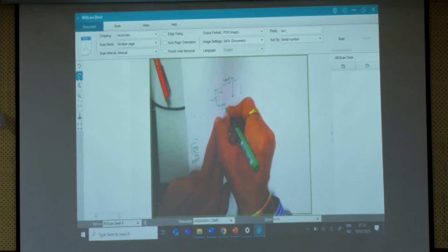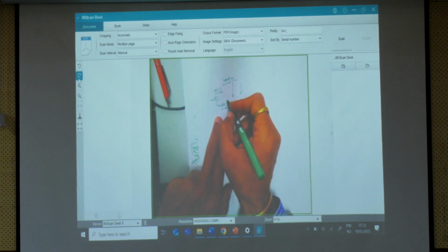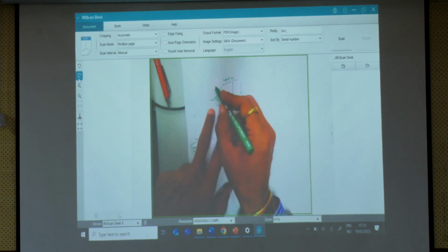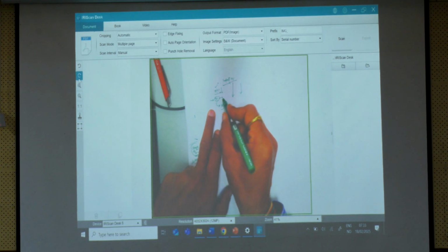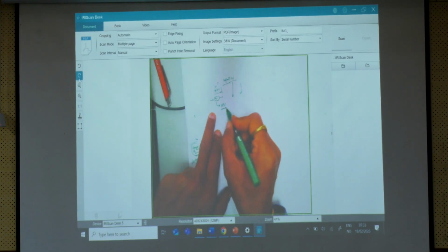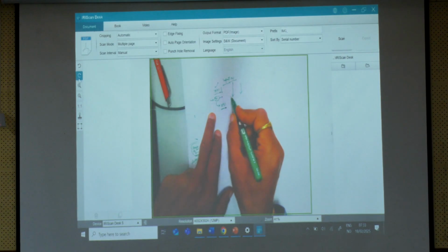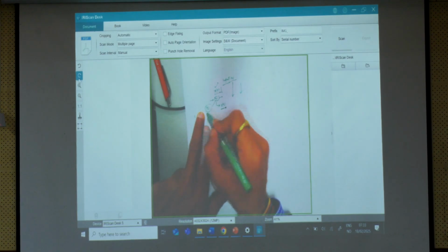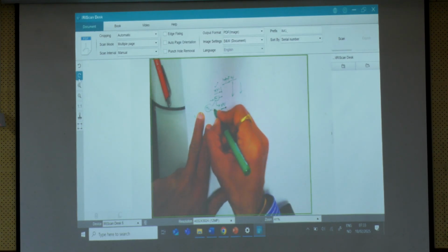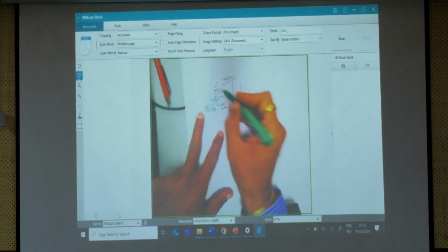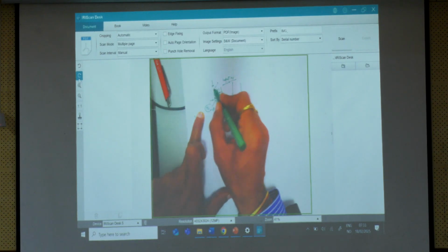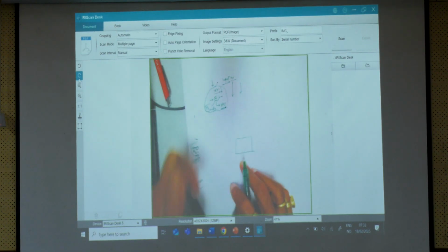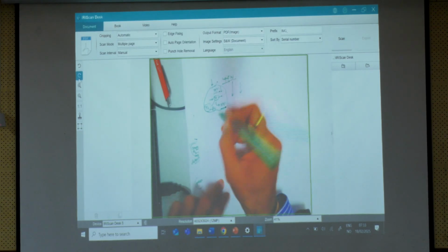There are a lot of models, they are available even in the MATLAB Simulink also. We can provide the input of the wind turbine and, providing the characteristics of the wind turbine, we will get the power output. In this case, our wind turbine is variable voltage, variable frequency, but that you cannot connect here. So, we have the DC output here which we connect here. But now, main input is this. This we will take as one complete model, and we get the P output here.